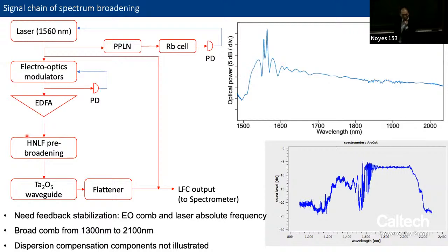If you calculate 200 picojoules per pulse with a repetition rate on the level of 16 gigahertz, it's roughly about 3.5 to 4 watts, if you also count some loss on the signal chain. And the pulse width requires about 100 to 200 femtoseconds, and that's pretty achievable with the nonlinear fiber broadening stage.